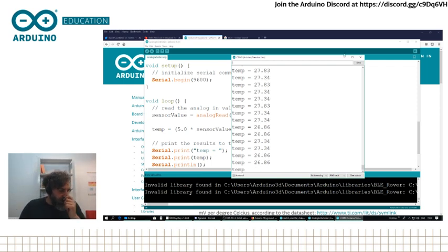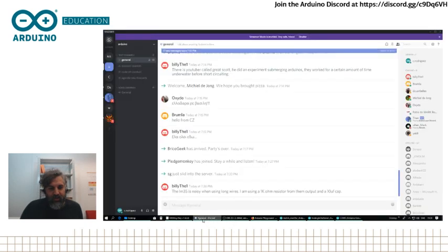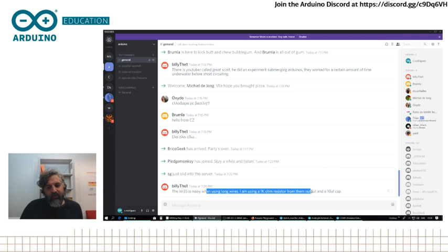So as I'm showing this, Billy from Greece is commenting here that the LM35 is noisy. We're using long wires. So I wonder, Billy, if you think that the wires I'm using here are long or short, because they are about less than 10 centimeters long. Anyway, he gives advice that people should probably take into account. I will just open here the channel. So if you use long wires, it's noisy. He's using a 1 kilo ohm resistor from the output and then a 10 microfarads capacitor. So basically this is making a low pass filter. This is what Billy is doing to ensure that the analog signal that comes from the sensor is not bumping back and forth, but it's filtered out. So thanks, Billy, for the tip.